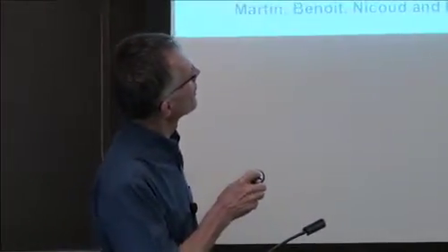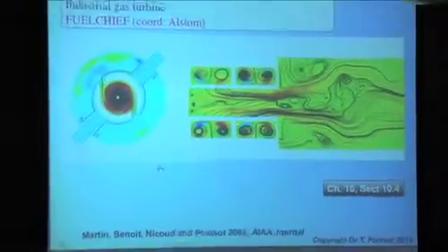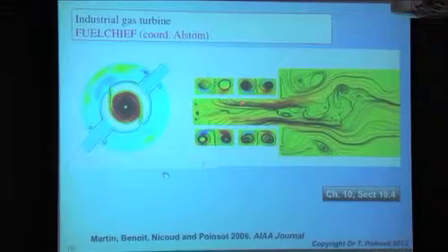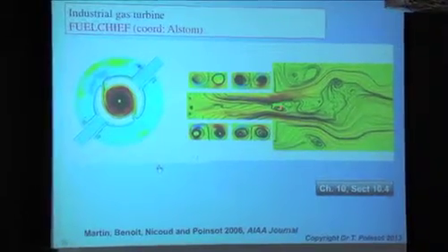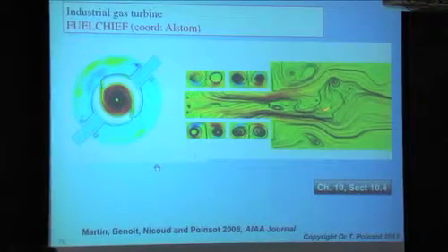I want to talk about another burner here, which was also a European project. And this one was installed in École Centrale in Paris. It's a more complicated burner in some sense because there are lots of injection devices here. So basically, this is a wall. You inject through this chamber by these devices here. And here you have a backward-facing step, and the flow is going that way.